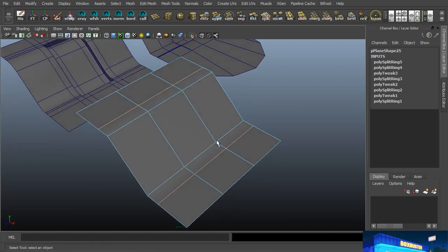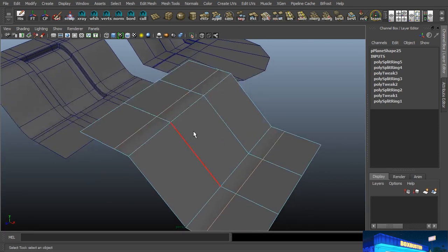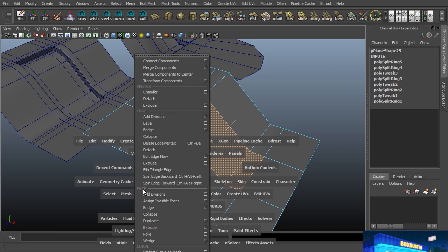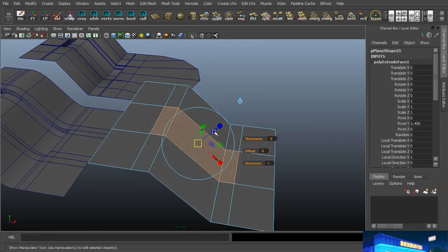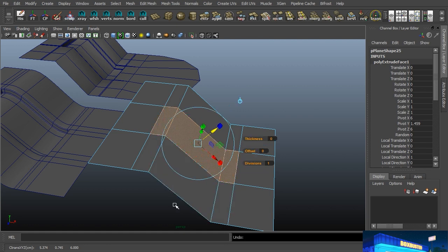All right, so we've got everything that we need to be able to grab these 3 faces and extrude them down. So let's go ahead and do that. Grab those 3 faces. We're going to go to Edit Mesh, under the face, and we'll extrude. Now, rather than pulling this down, I'm going to do something a little bit different because I'm not really sure what this handle is going to give me. It generally goes off of the normal direction of the surface, but I don't usually trust that it's going to give me what I need.